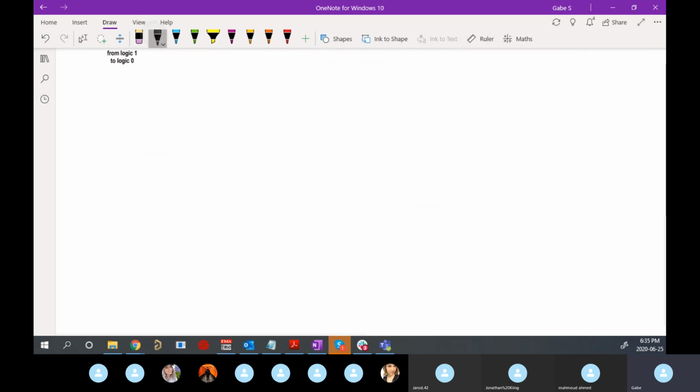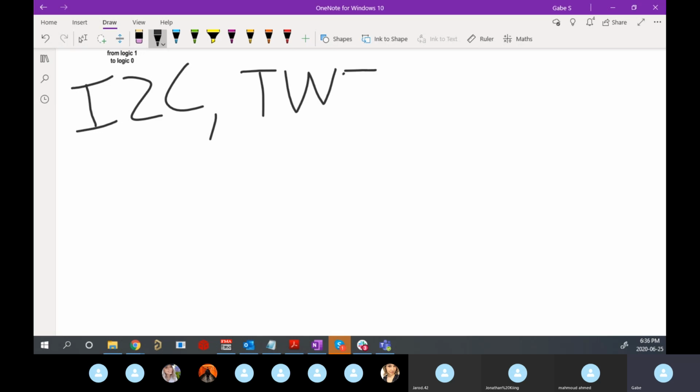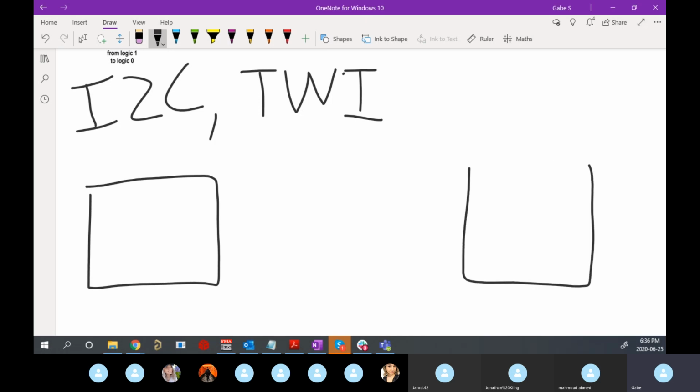Great. So with UART out of the way, we can talk a little bit about I2C. Some people call it I-squared-C. Those people would be wrong. I'm just kidding. Sometimes I call it that as well. Some people also call it TWI. I don't see this very often, but two-wire interface. You'll see that sometimes in old school data sheets. But the idea behind it is similar to what we just saw in a way, because we also use 2 wires.